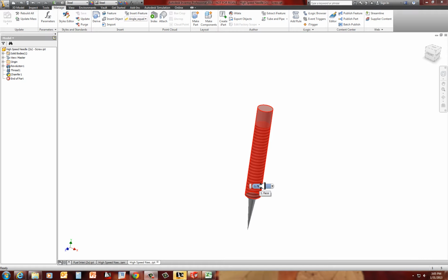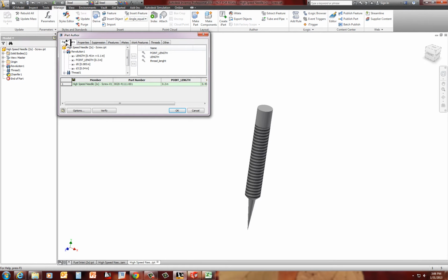And if you notice, there is a top that's separate from the high-speed needle. We're going to look for a press fit between those two materials, and we're going to calculate what that hole needs to be in that top. So you need to make those two different pieces, and they also have two different diameters, so we'll make them an iPart as well. An iPart essentially uses different parameters that you put in, and you can change those as you add them over here.